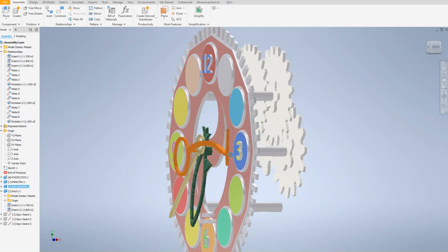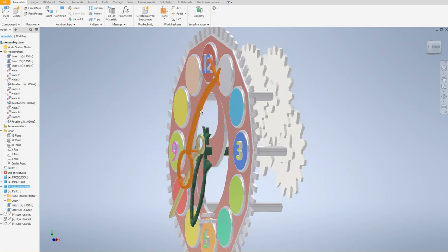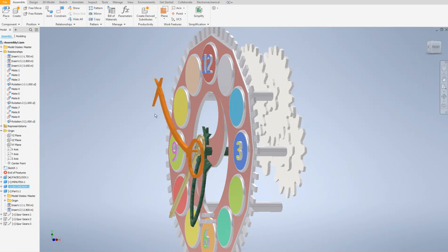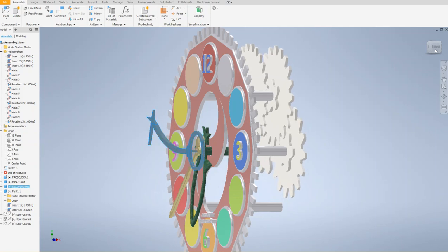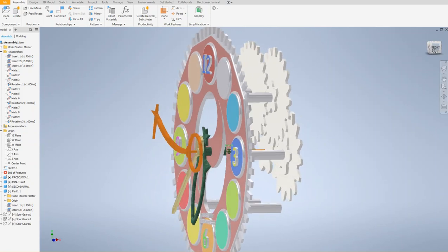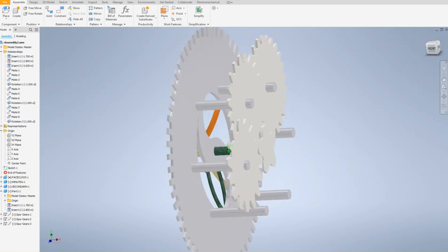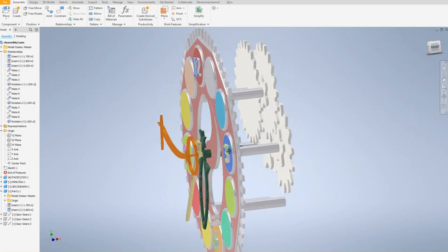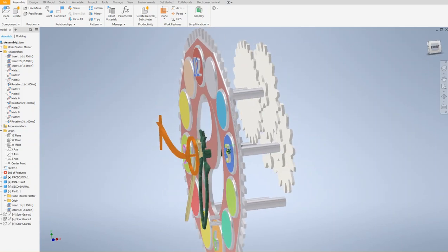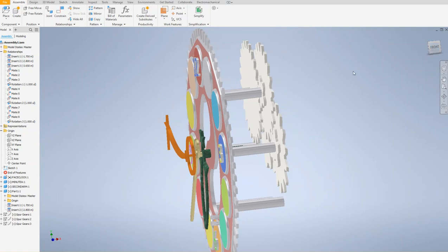So when you rotate that, it turns the larger gear, and as you continue rotating, small gear rotates larger gear, which rotates small gear, and small gear rotates larger gear, in that order. So basically the motion is going to be slowed down, which is the purpose of that.